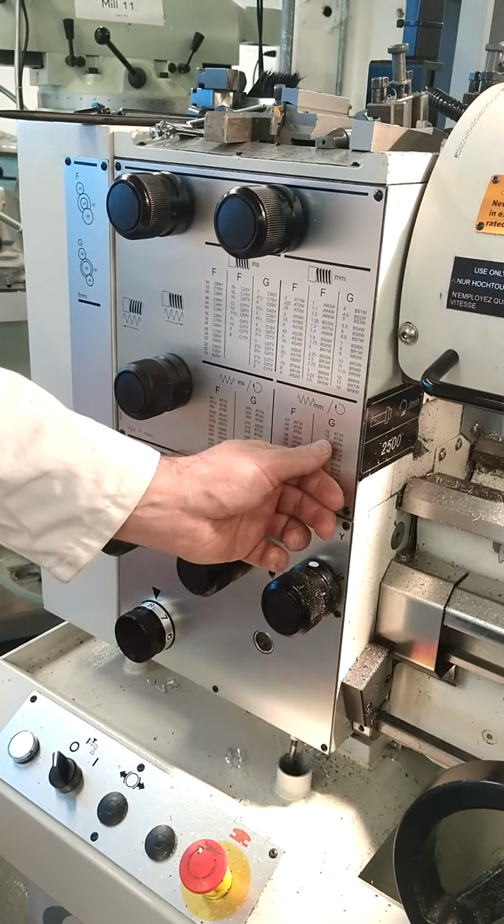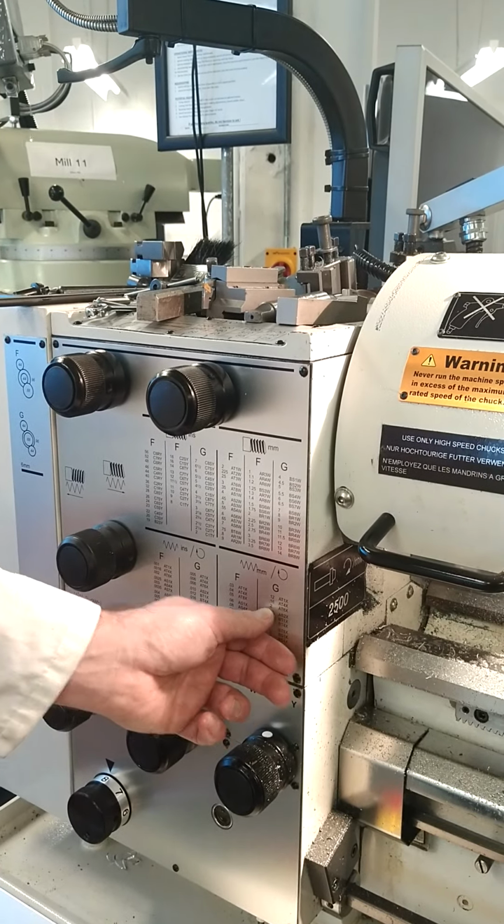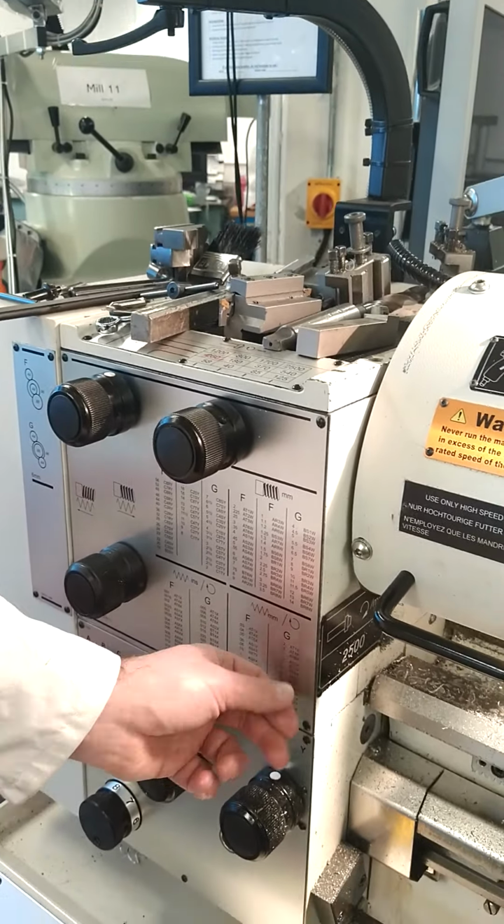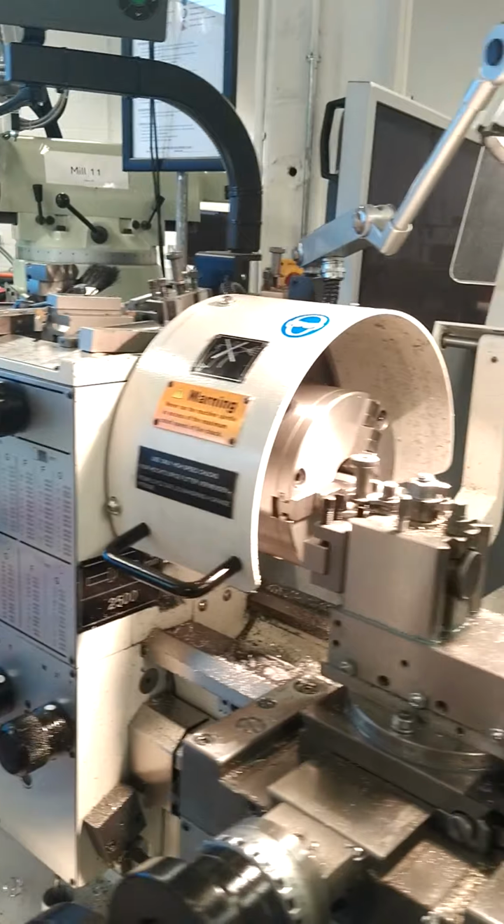So the formula is the RPM, 260 is the RPM, times 0.2, times the number of cutting teeth, and you've only got 1 cutting tooth. That gives us the distance, how fast we're traveling. So 0.2 times 260 will give us the feed rate. If you increase the RPM while holding the same feed, the same gear chain, it will obviously go faster. If you increase up to 1200, the automatic feed will go faster.